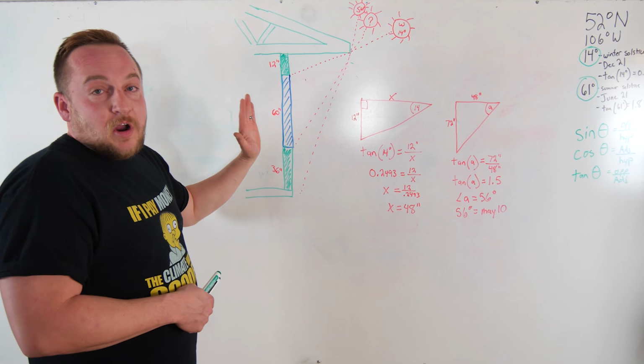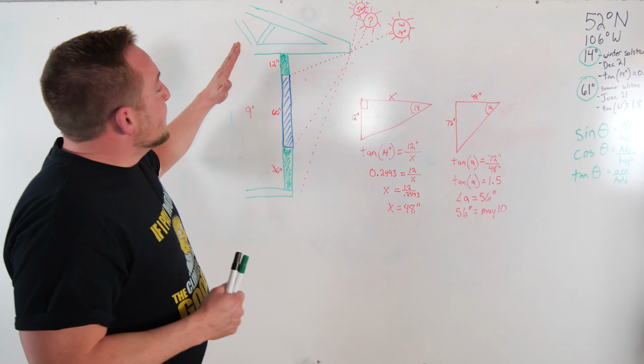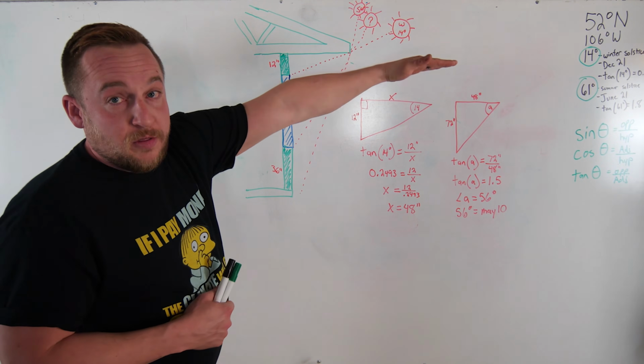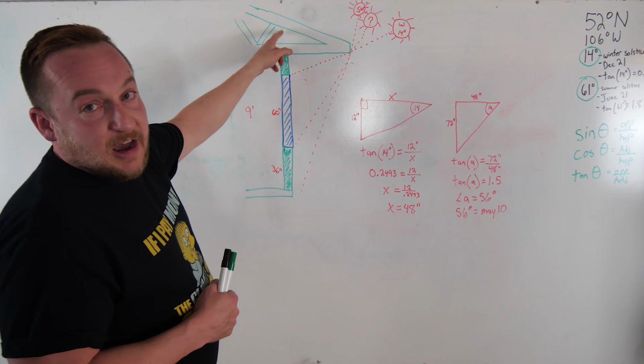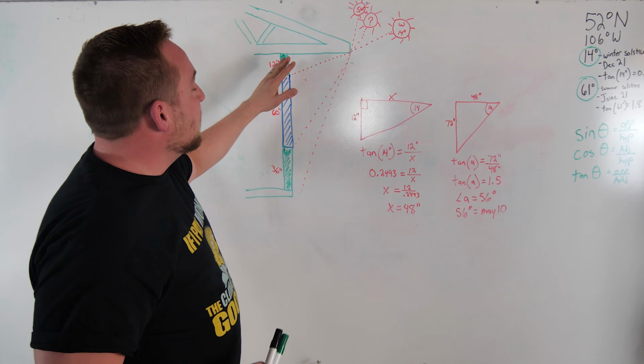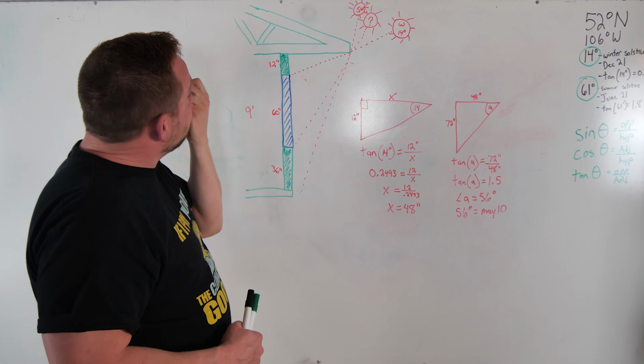So here's a diagram of my house that I built for myself with my two hands, and I designed it myself. It's designed perfectly as a passive solar house. My house has 9-foot ceilings. This is south. After I did these calculations, I had my trusses structurally engineered at the truss factory for the load point to be exactly over my wall.